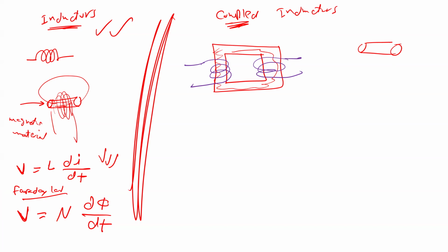Okay. And then here you can have a circuit. For example, I can put a lamp here, and a voltage source here. But this voltage source has to change, because otherwise it does not work. You can see even here, don't you guys? Because we have differentiation. If this flux is constant, this one is zero as well. So it should be AC, not DC.